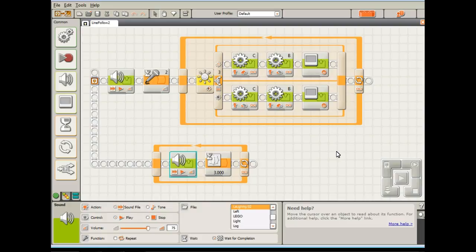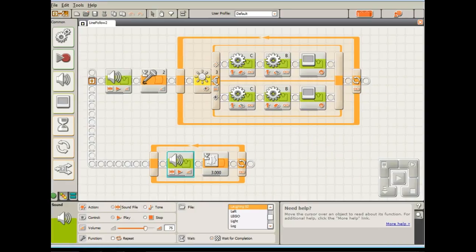You say, well, I could put it in a program to hit the gray button, but there's really no need to put it in a program if you're going to have to do it anyway. So what you do to stop the program is you pick it up and hit the dark gray button, and as soon as you hit that, the program will stop. That's a good question. Normally, if we have a loop, sometimes we put something that stops it in there. With a straight line program, when it gets to the end, it stops. Since we don't tell it to loop, when it gets to the end, it just stops.